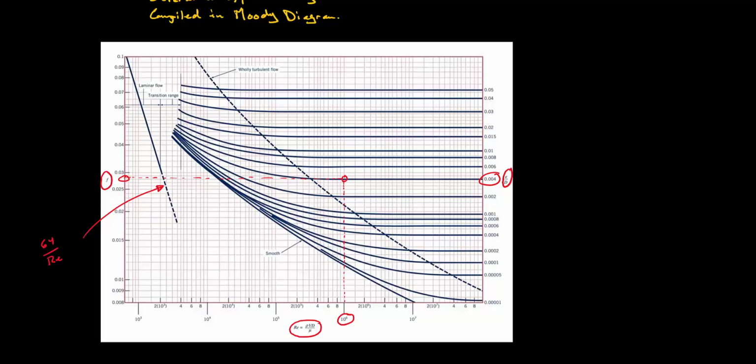Okay, so in this video, what we have done is that we have looked at the pressure drop between 2 points, given a certain pipe section, length L, a diameter D, and a flow rate Q. We applied control volume analysis, and we were able to carry out this control volume analysis for a laminar flow because of the fact that we have a nice analytical relationship for the velocity profile of a laminar flow. And what we found is that the non-dimensional pressure drop has the form of a friction factor multiplied by the ratio of the length over the diameter.